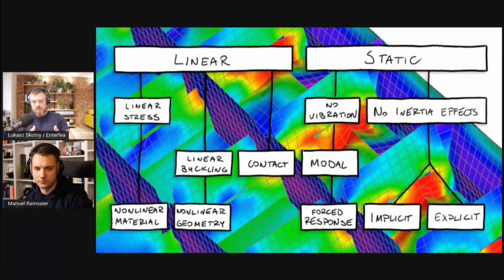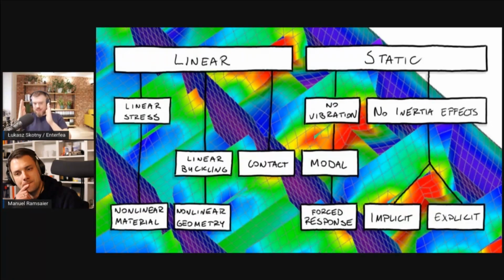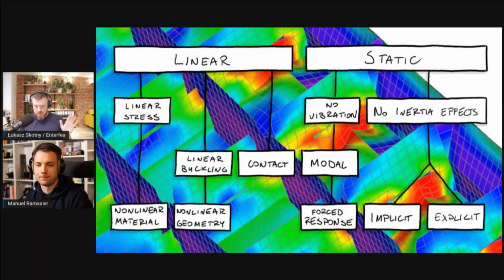The biggest problem is that this extra bending bends your element even further, making the imperfection even bigger. And then you compress again, and effectively you are wondering, will this stop? So the incremental increase in imperfection, will it stop at some point and be stable, or will it cycle to death and fail? And this is something linear buckling just cannot see.